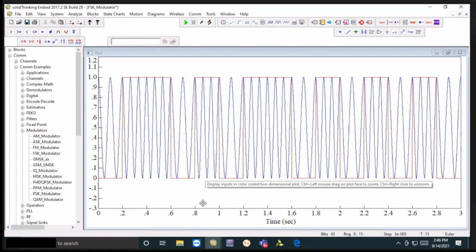So here you can see that the carrier frequency we have taken as 10 hertz and the delta value we have taken as 5 hertz. Okay, and we have taken the unipolar signal, you can see it is going from 0 to 1, right? So when there is zero value, 0 into delta will be 0. So you have cos omega t, that is cos of frequency value 10. So accordingly you will have the signal and there is no change in the carrier frequency.